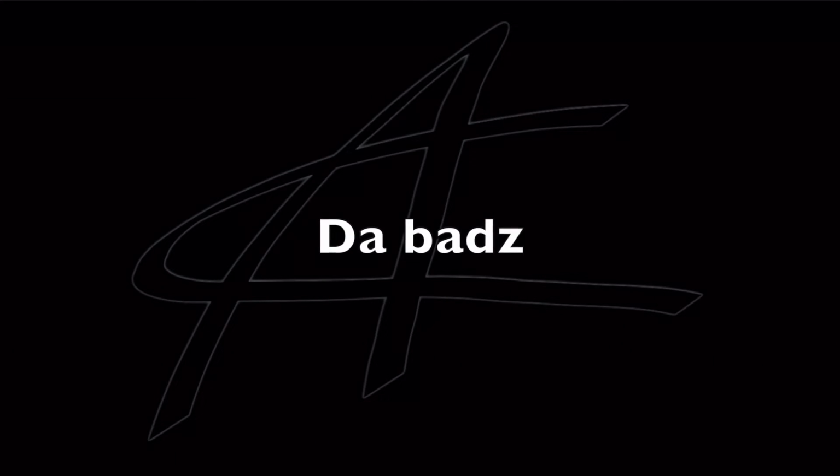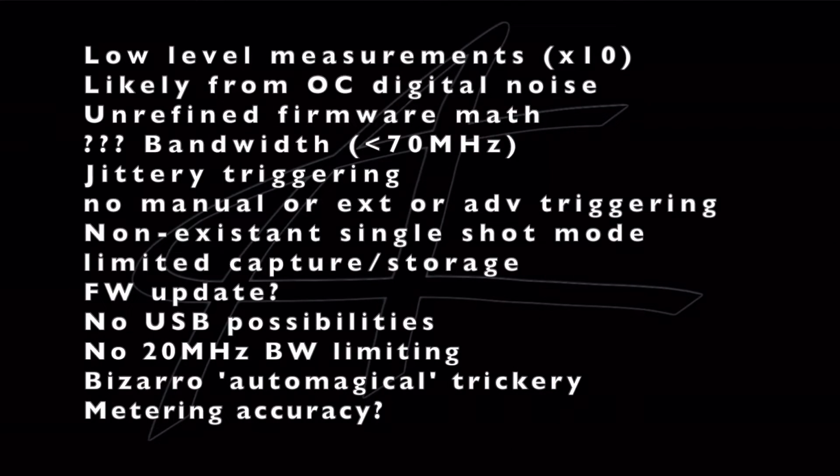So, the bad stuff. And again, this is first impression bad stuff. This could change, or the list could grow depending on more in-depth usage and investigation, but low-level measurements with a 10 times probe are probably not going to happen. You could put a preamp in front of it, but that's a lot of gain. It's likely that's from the overclock and digital noise and jitter and all that stuff. They didn't want you to go down that far. I have no idea, but since the firmware is not open source, we can't change it to find out. The firmware math is obviously unrefined. You can see that in the waveforms and whatnot.